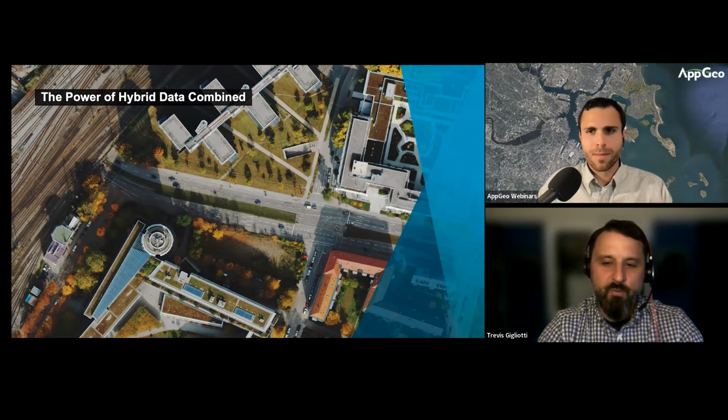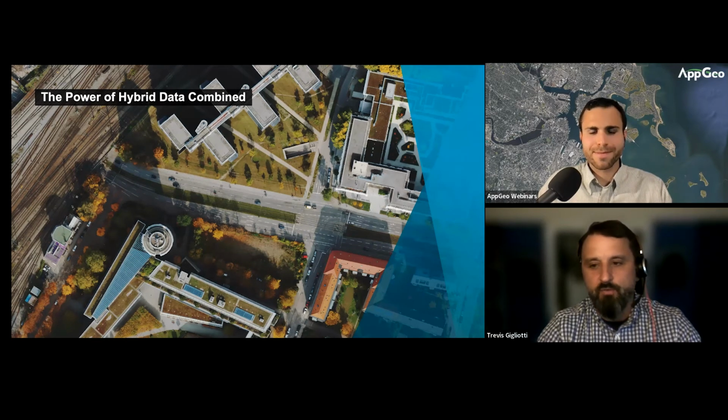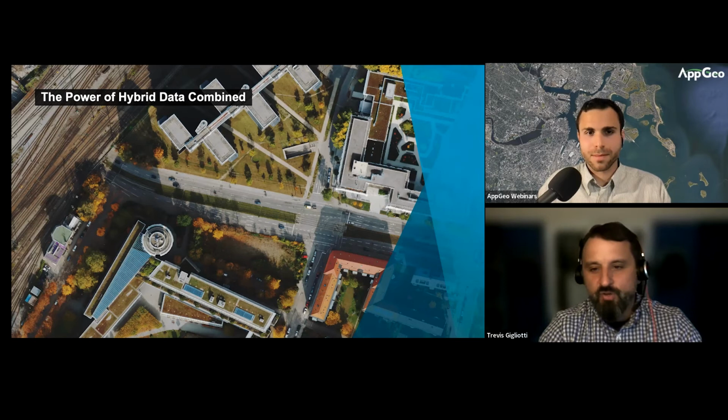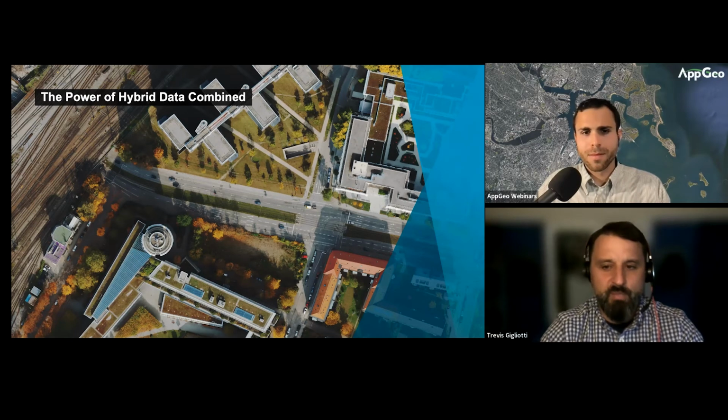Once you've removed building lean, that means you're removing the occlusions from seeing sidewalks and streets. So you're able to better extract building footprints or see the street furniture and infrastructure that's on the ground. It really makes an ideal tool for urban planning or even extended feature extraction. Like I said before, this is delivered as a 2-inch or 5 centimeter product for spectral bands in GeoTIFF format, and it's also tiled for delivery.